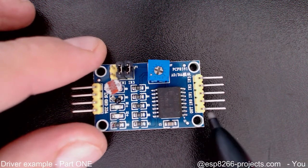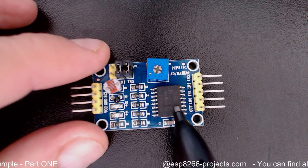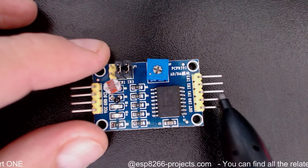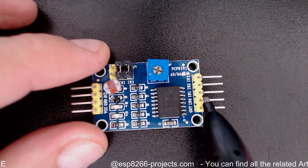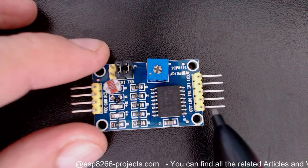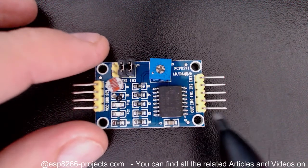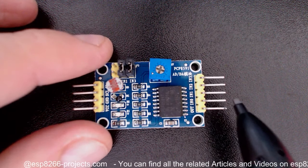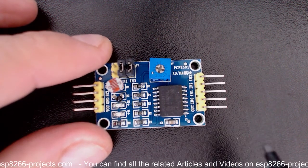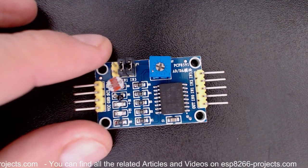So basically what we will try to do will be to set a voltage here on the DAC output, and after that we will try to read the voltage on the ADC input, and we will take a look on the results to see exactly how accurate this IC is and what's the difference between the output voltage of the DAC and the input voltage that we will receive on input 0 of the ADC.